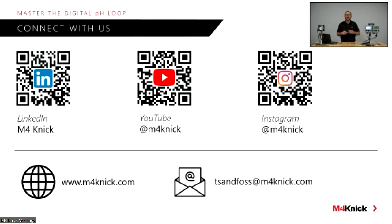When we talk about RS-485, not to get too into the weeds, but on a Memosens cable, you have 4 conductors in a shield. Of those 4 conductors, one is for powering the sensor, very low voltage. Memosens is intrinsically safe. So one of those conductors is power for the sensor. The other 2 are your RS-485 for your communication, both A and B. And then you have a ground wire and a shield.